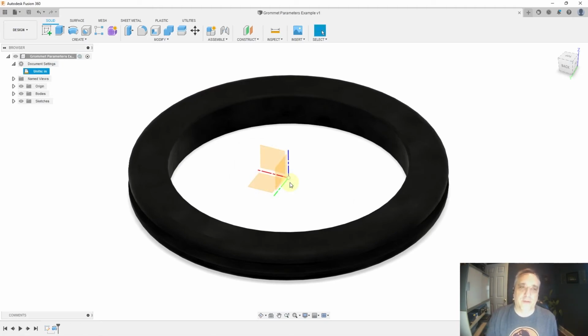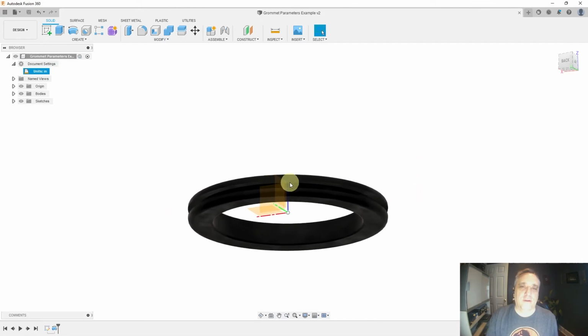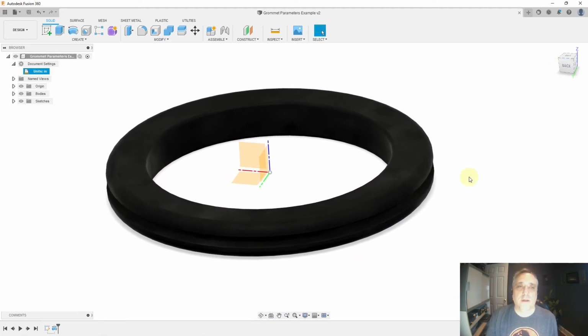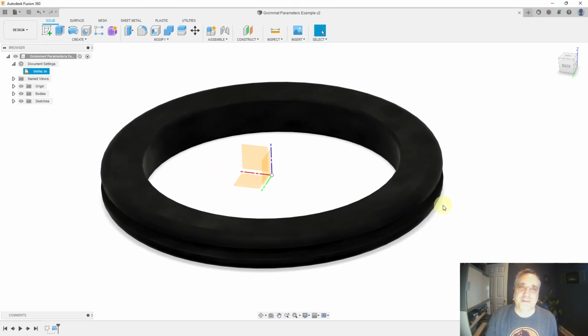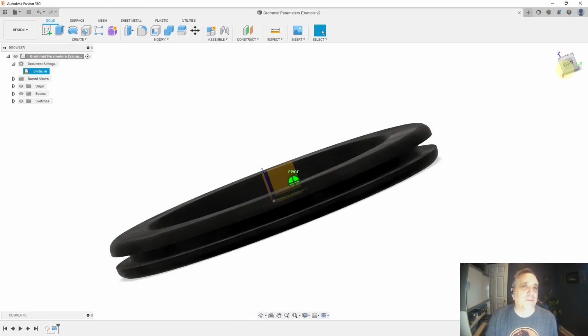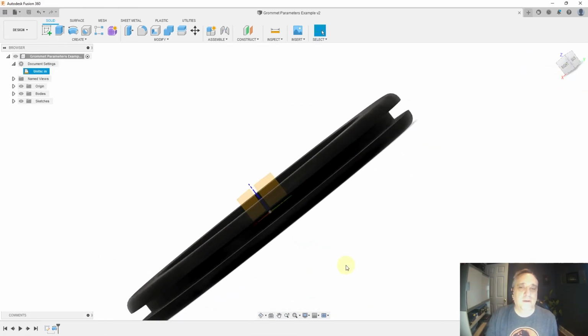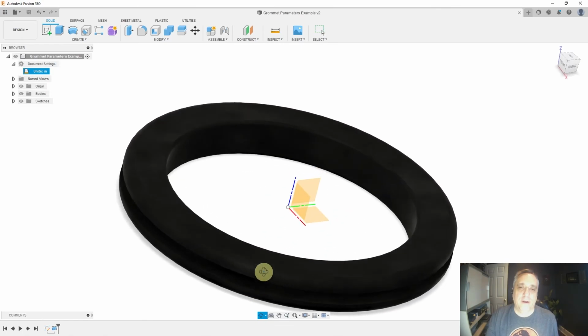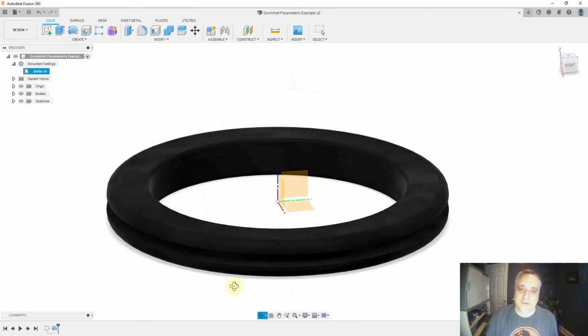So you'll notice something here as I'm working on this. I'm rotating and zooming in and out, and I'm not using the orbit tool or the directional orbit tool up here. It's because I have a space mouse. These are handy, especially for snapping in and out of different views. I love that. You can click on this to get it, but I'm a big fan because you kind of get out of whack really easily. This tool is all right. It works a little bit better. You can still get kind of out of whack. But the other issue is once you're in it, you have to escape out of it. And I like to be able to click and move at the same time, so I use an orbital mouse.